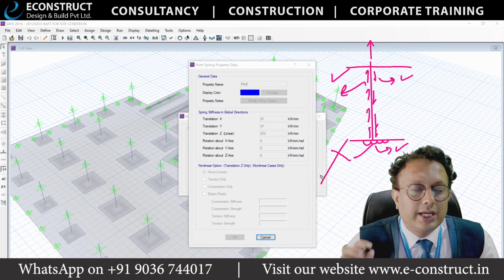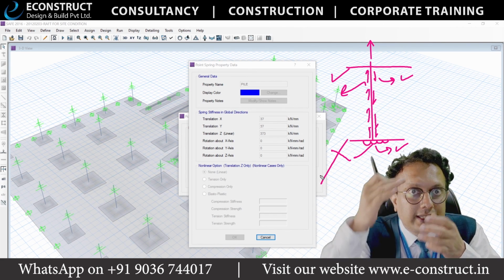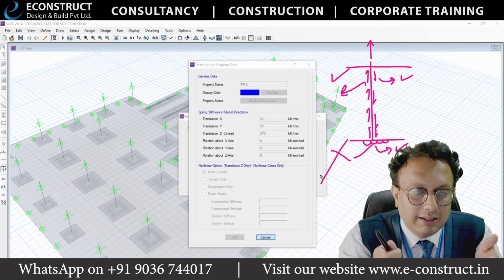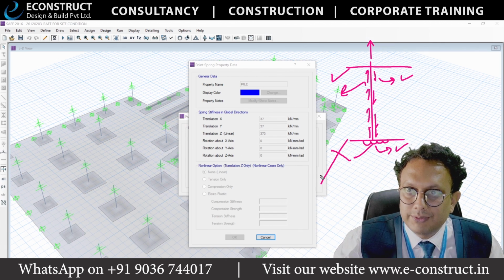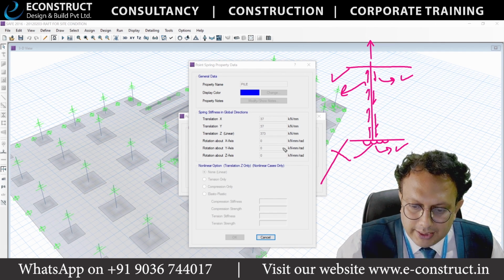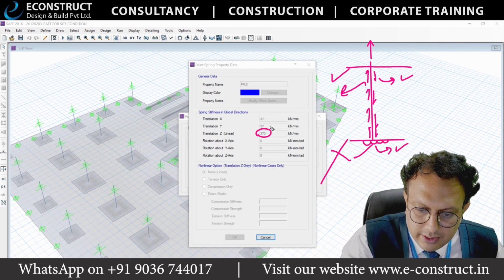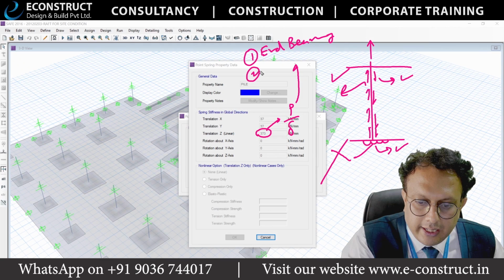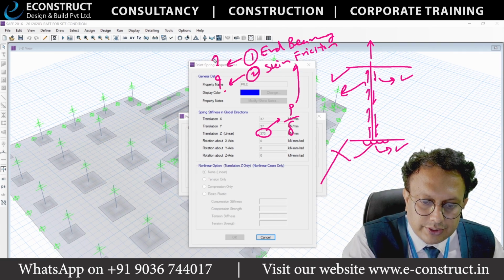You need to deduct the end bearing. So you need to take the component of the end bearing, the pile capacity constant I am saying. What is the capacity constant? It is P divided by delta, right? So P has two components. The first component is end bearing and the other component is skin friction. So you need to ask how much is this and how much is this.